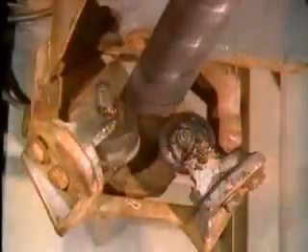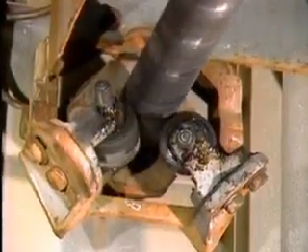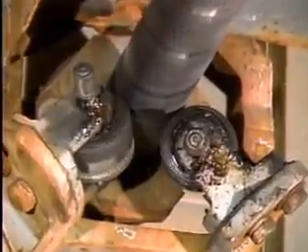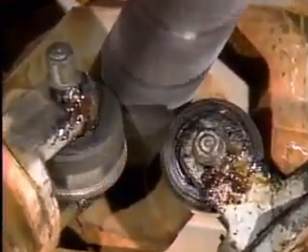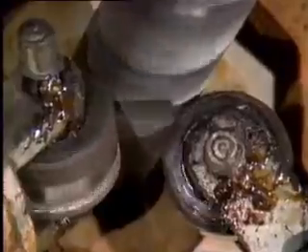The rollers support a device that's used to clean the tubes inside an operating boiler. Heat from the boiler is transmitted to the rollers in the grease. Grease made with ordinary thickeners would melt and drip out of the bearings, but the bentonite resists high temperatures, so it keeps the grease from melting.